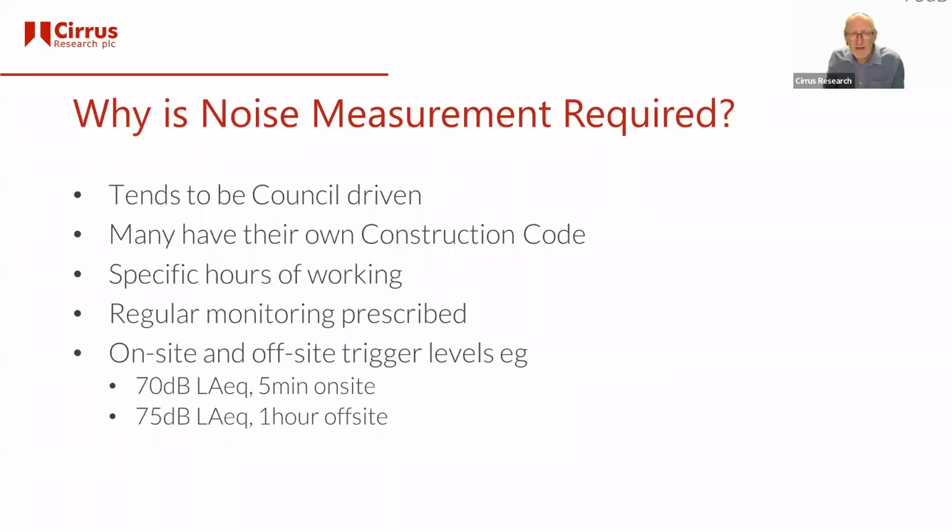So just to summarize, the noise measurement side of it tends to be council driven. If you've got any site, why would you spend money on measuring noise unless it was absolutely vital, unless you're going to be a good neighbour. So many councils have their own construction code. They have a lot of useful information and documentation that you can look at. And the type of things they will enforce are the specific hours of working. So, only working Saturday mornings, not working on Sundays and bank holidays, limiting the time that you're working during the working week, typically from 8 till 6, that sort of timing.